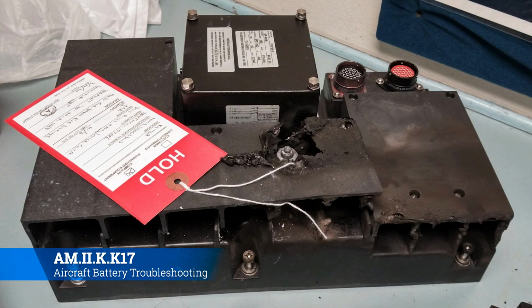Okay, discolored or burned connectors or internal connectors. That means a dirty or loose connection, or improper mating of parts. Now, I've actually seen aircraft catch on fire from this exact thing. If you think about a wire, right, if you have a lot of power going through a wire, and that wire is super thin, well, that wire is going to get super hot, because you have the same pressure, the electromotive force on one side, pushing everything to go through this really skinny wire.